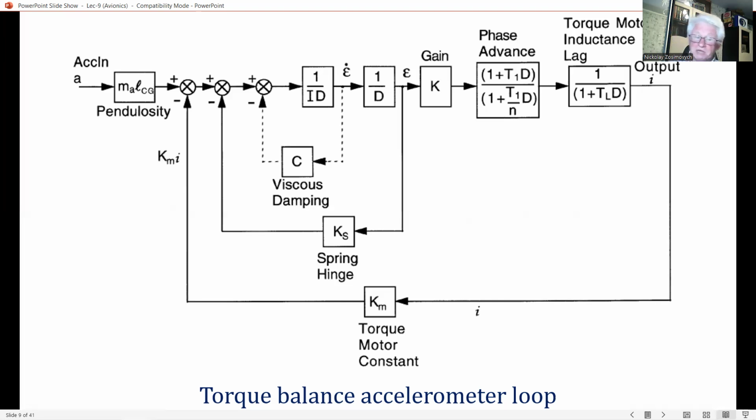The accelerometer loop gain must be sufficiently high to keep the pendulum excursions from the null position very small under the vibration environment. Significant rectification errors can otherwise be introduced, as the accelerometer will sense a component of the vibration at right angles to its input axis, which is proportional to the pendulum displacement from null. A simplified explanation of this is set out below.